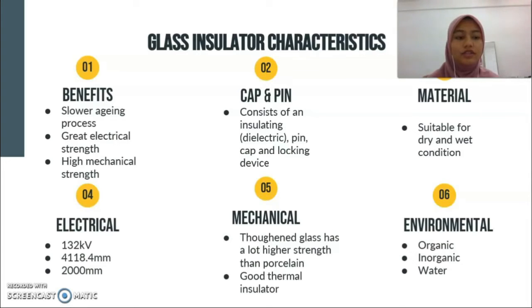For the electrical characteristics, there are several calculations that have been made: the system voltage is 132 kilovolt, the creepage distance is 4,118.4 millimeters, and the length of the insulators is 2 meters.